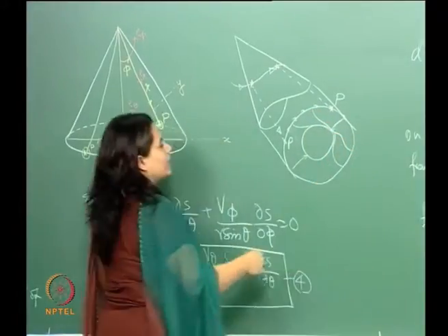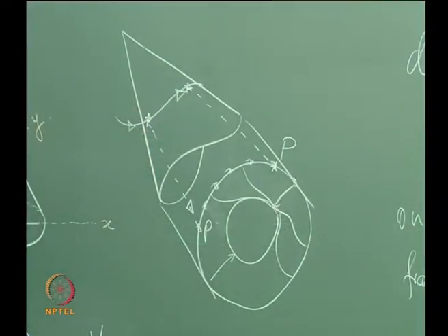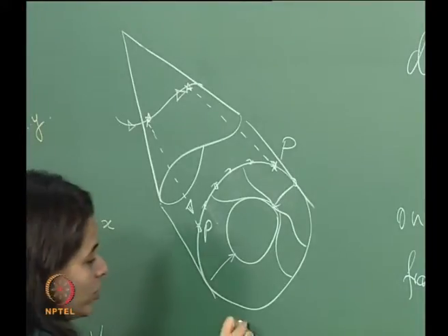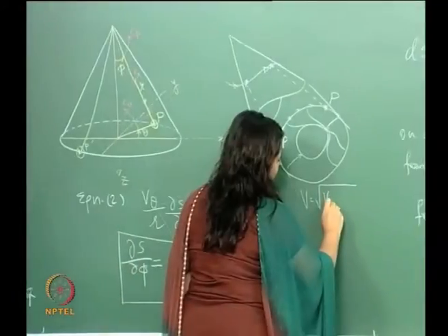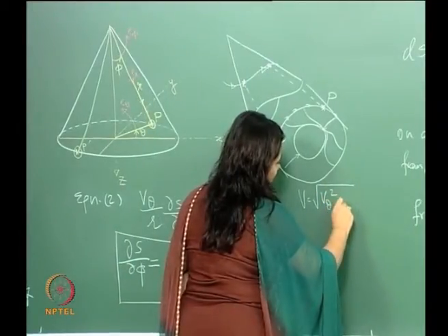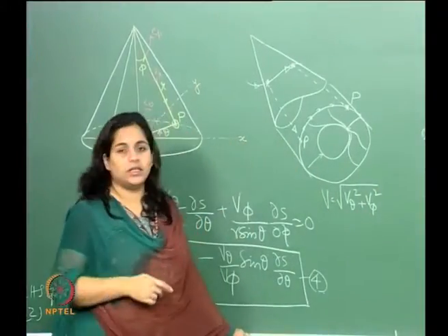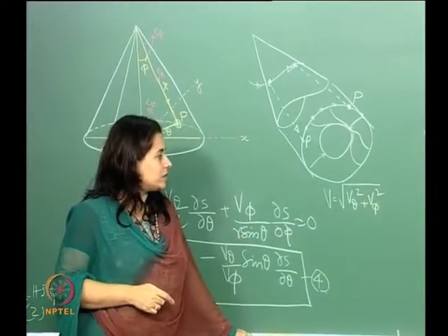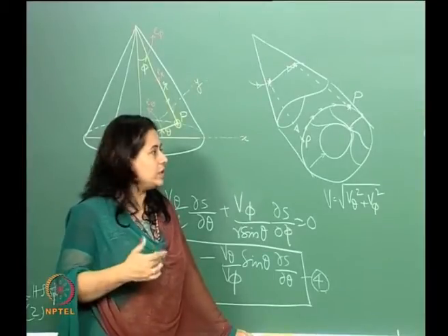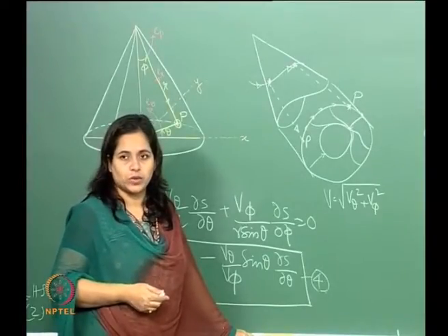So on and so forth, we had all sorts of things. So, this plane is called the cross flow plane, and the velocity that we had talked about, this v theta v phi in this plane, is the cross flow velocity, and when this goes to 0, then you have a stagnation point.